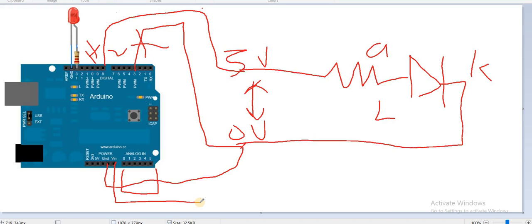The voltage should be higher than 5 volts, because from this pin the voltage will pass through a voltage regulator that will convert the voltage to 5 volts. And if the voltage is not up to 5 volts already, it will reduce the voltage, and it is likely that the microcontroller will not be working perfectly if the voltage is lesser than 5 volts.